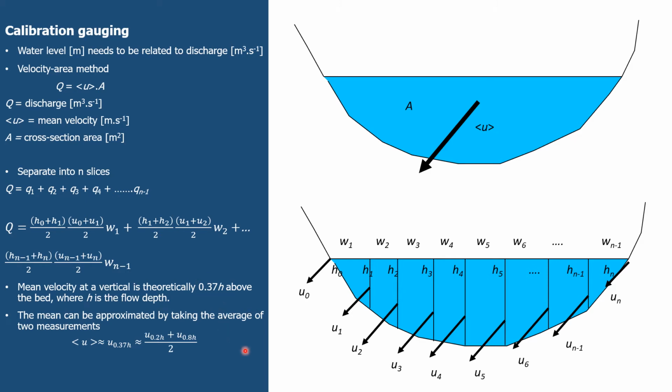If we do this using an ADCP, the ADCP essentially does the same. It does a numerical integration of measurements of depth and velocity to calculate the discharge. The software within the ADCP is solving this equation and putting numbers into that equation, but it's doing it almost continuously rather than in slices. The same approach, though, in order to get the total discharge.